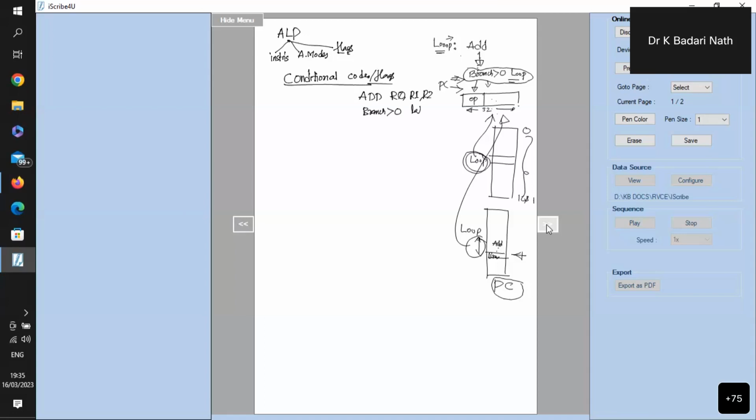Any time you execute an instruction, there is a very good chance that you may use a branch instruction to implement if and else, for loops, while loops. That means anytime the processor performs an arithmetic or logic instruction, it is required to set certain information in the processor so that a later instruction can look at that information and take a decision.